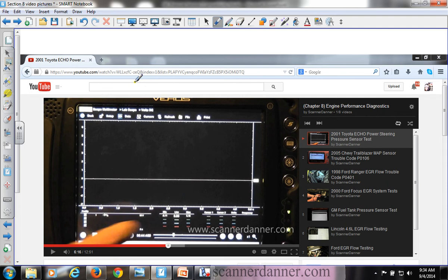An open in the signal wire, though, we would be at 5 volts here because we're measuring at the sensor. If we were measuring at the computer, the 0 volt signal open could be there, but because we're measuring at the sensor, it would not be, because of the way the circuit's designed. You follow that? What's the easiest way to tell at first look? What one's the signal wire and what one's the reference? Oh, that's a good question.